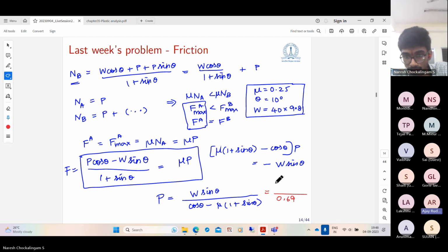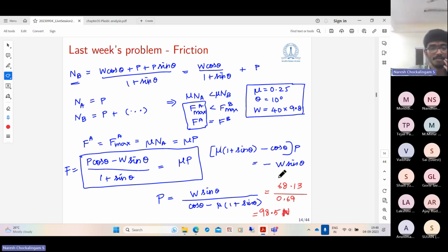So W is 40 into 9.81 into sine 10 degrees. Sorry, sir, it's 98, 98.5. Yes. So the correct answer is 98 point something, 98.5 kilonewtons. Sorry, newtons. So that is how you solve it.